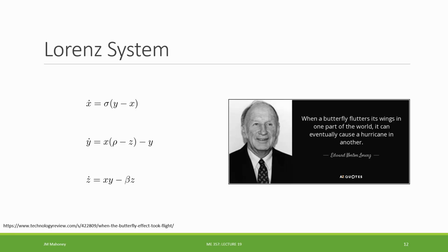So we're going to see a little bit how we set this up so that we can solve it numerically in MATLAB, or a lot of other solvers are going to operate in a similar way. We can still use tools like ODE45 to solve this. The difference is we can't set it up in matrix form. We're going to have to explicitly put what the x dot, y dot, and z dot equations are in order for ODE45 to be able to handle it.